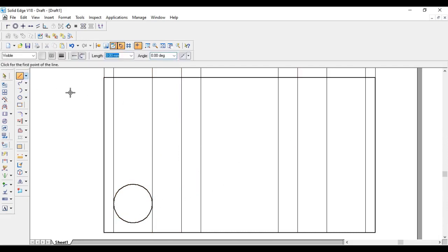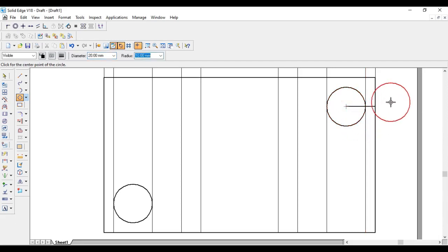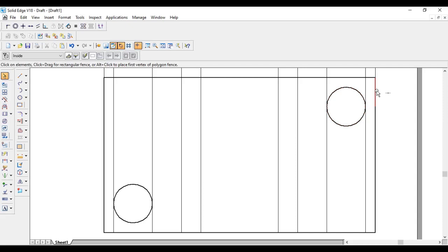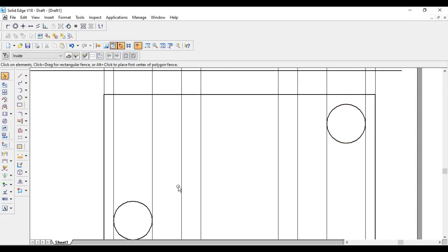So similarly, in the opposite corner, from this tip you take a length of 15. Since it is 15 away, here also you take a 15 straight line. You can simply join or take the circle tool from the tip of that one. You just touch to the projection lines from the front view or enter the diameter 20. So it is exactly that circle. Right click to deselect that one, select these 15 lines, then delete those lines. So this is the one part.